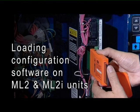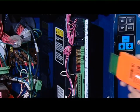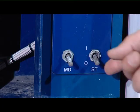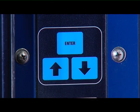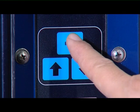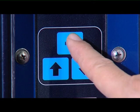Loading the configuration software on ML2 and ML2i. Switch off the unit and insert the adapter with the card. Switch on the unit. The card contains the following files: the configuration file, software number 1207, software number 5132. Using the arrow key, select the configuration file and press the Enter key to confirm. The display will show once again, Press Enter. Press Enter.